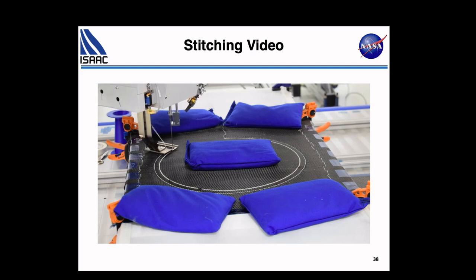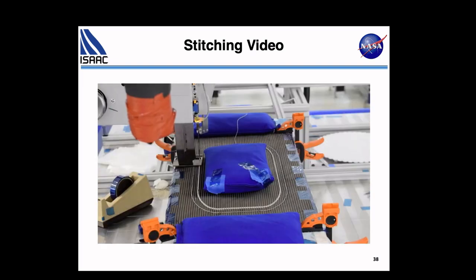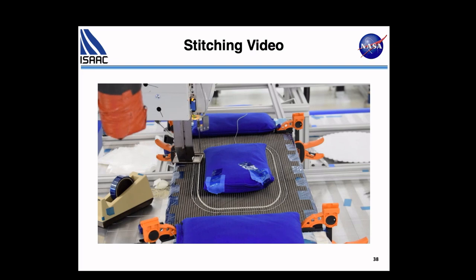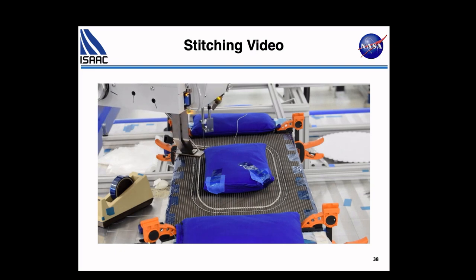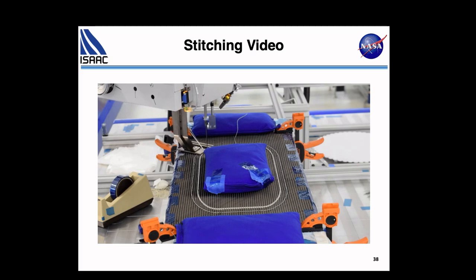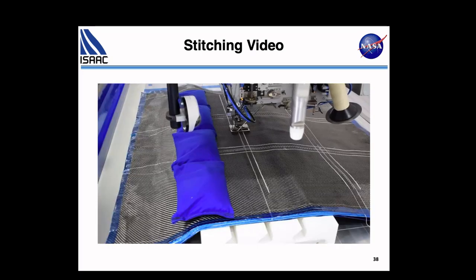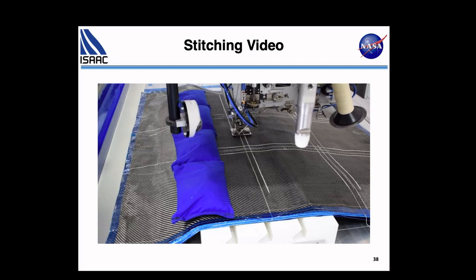If you think about sitting on the airplane and the window belt, if you could stitch around each of those windows, then that's less material you might need to have around those windows, because normally you would have to put in doublers because you're going to have to drill holes in there because you've got to put a window frame and all. By putting the stitching in, perhaps you can avoid putting in those doublers because now your holes can be contained, and even if damage does start at the hole, it can't go anywhere. And so that's where we're trying to develop technology with particular applications in mind. And so it's the window, it might be an access door on your wing. There's lots of potential for that activity.